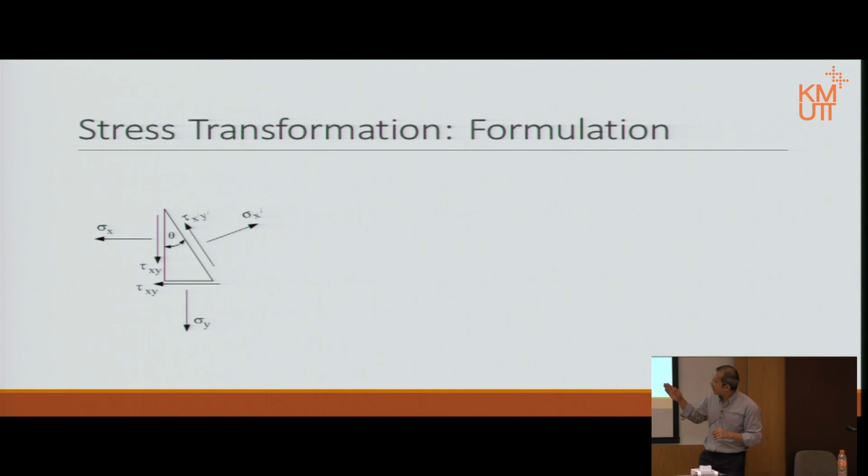And I said, if it is along the x prime, y prime, then the stress will become sigma x prime and tau x prime y prime. The rest is acting the same. Now, notice that the symbol here hasn't changed. The reason being, when you cut the element, these are the stresses which are distributed all over the area. Therefore, the magnitude doesn't change, it just covers a smaller area down here, that's all. Now, this is the stress pattern, the stress symbol, meaning we cannot use sigma Fx, sigma Fy yet unless we know the area it is acting on.